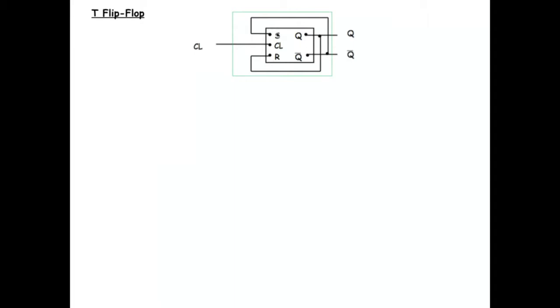The regular flip-flop had just S and R. The clocked flip-flop is the regular flip-flop with S and R and the clock outside with the 2 ands. I pushed it in to review it; you can go back to previous slides. Now it's inside, and we call that a clocked flip-flop, where we have set, reset, and clock.